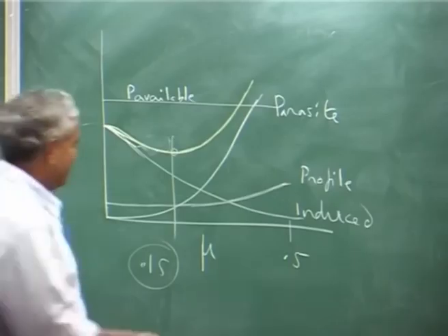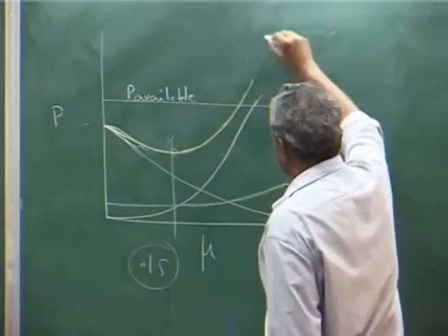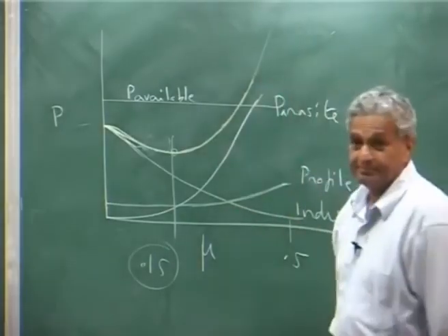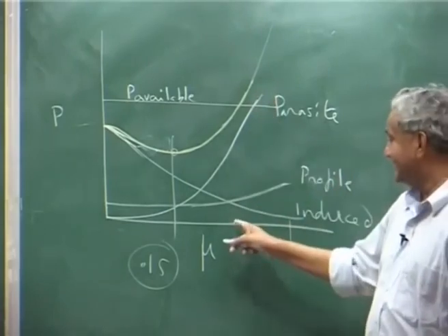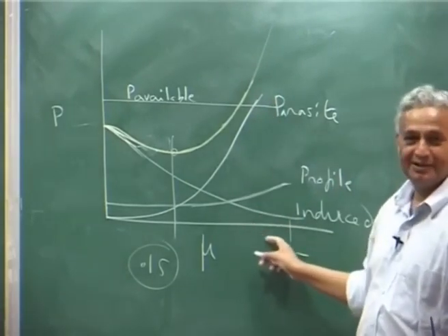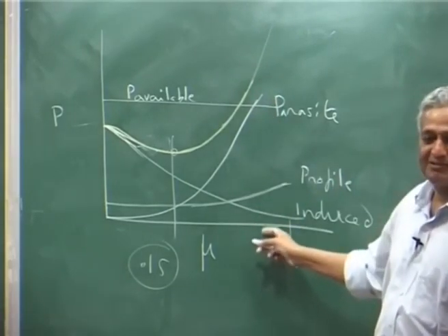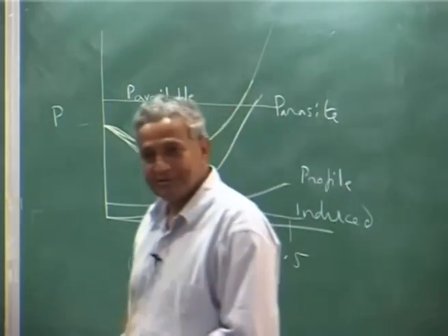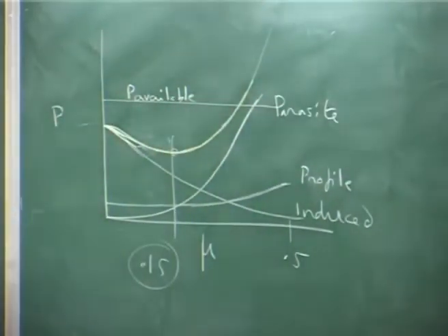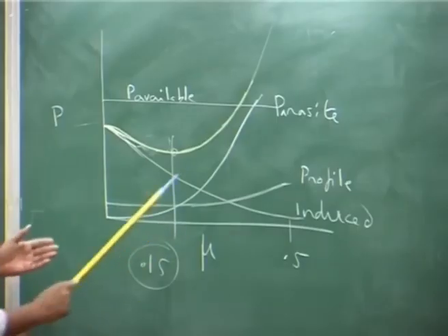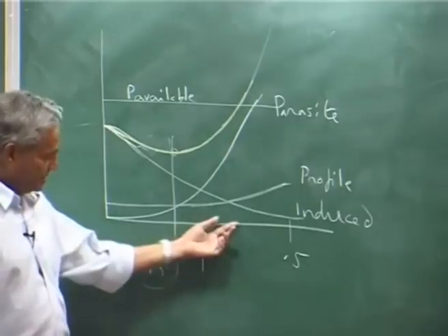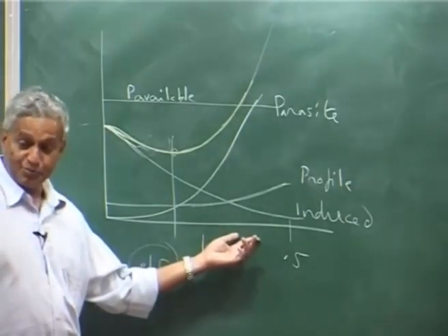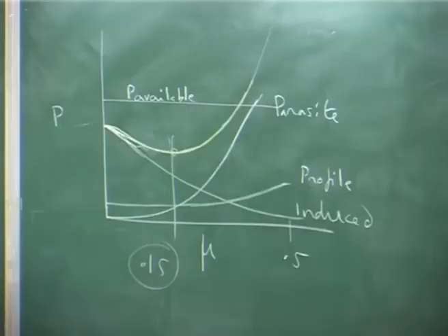But you see this power curve, this rises very sharply. You just cannot fly beyond that speed, because the power required will be tremendous, you will not be able to do it. So, you will find this curve will shoot up like this, the power required will be much more, that is number one, and your vibratory loads also will increase very high.